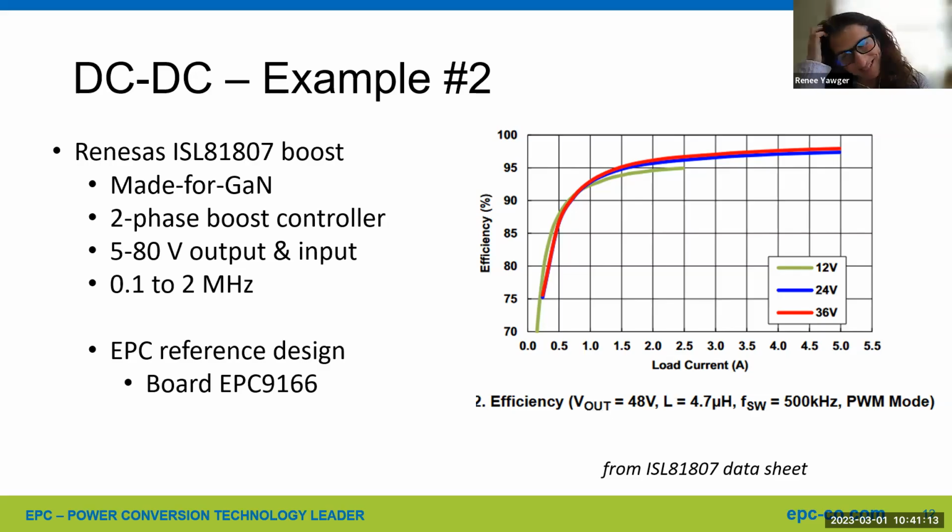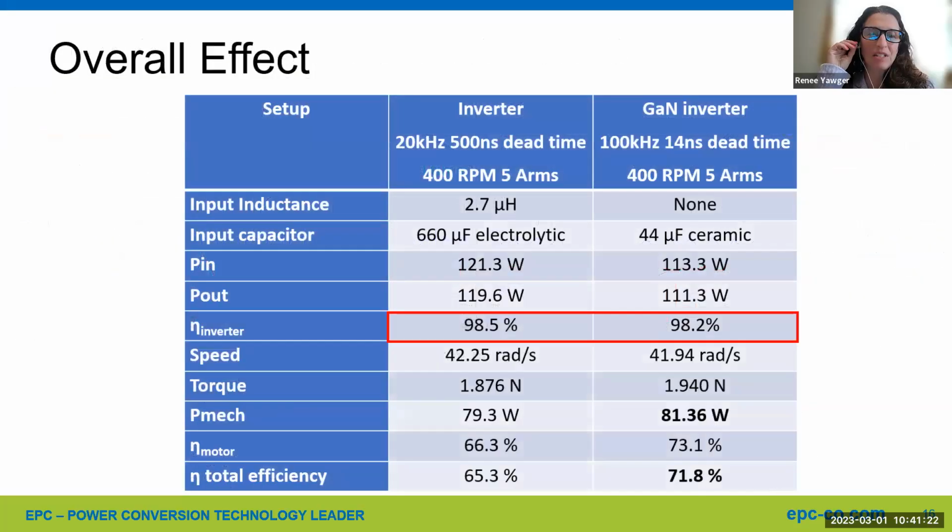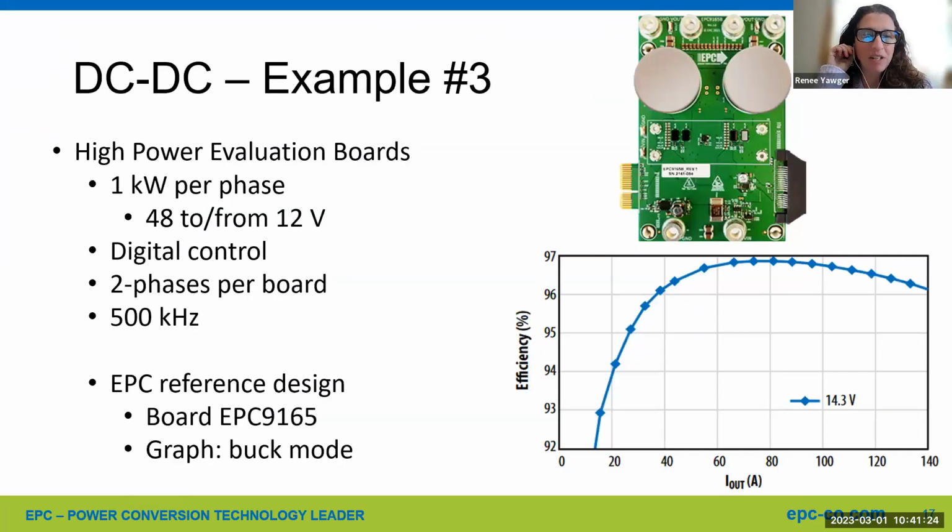All right. In example 3, is it easy to put the GaN components in parallel? Is the behavior good? And is the current separated well in each arm? Yeah, let's cover these one by one. This particular board has just one FET per position. So there's 2 phases, so there's no paralleling directly on the FET itself on this board.